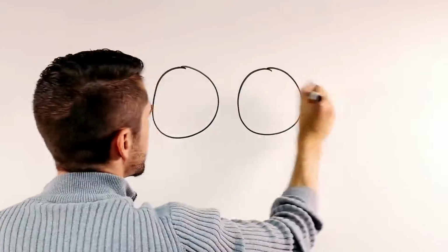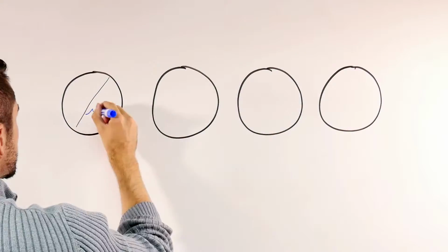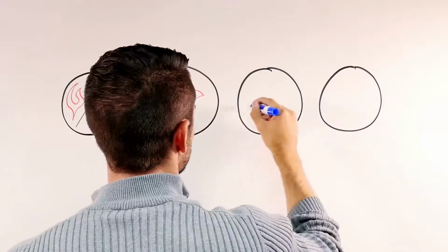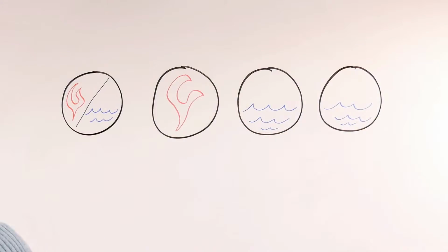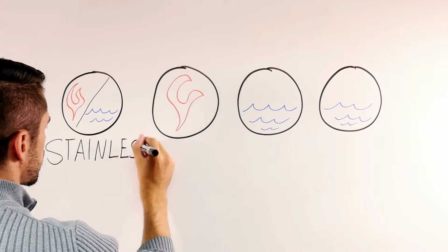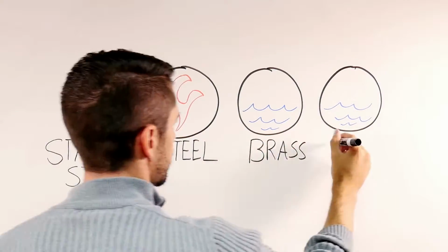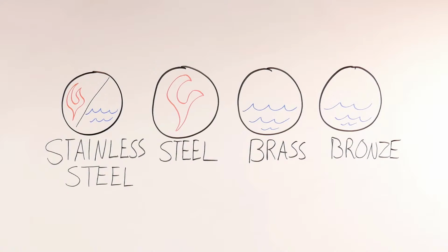The metals the hinges are made from are also an important factor in selecting the right hinge for an opening. Steel or stainless steel hinges must be used on fire-rated openings. Brass, bronze, or stainless steel hinges should be used when the openings will be subject to corrosive environments. If the base metal isn't the desired color, most manufacturers offer plated finishes to match an opening's other hardware.